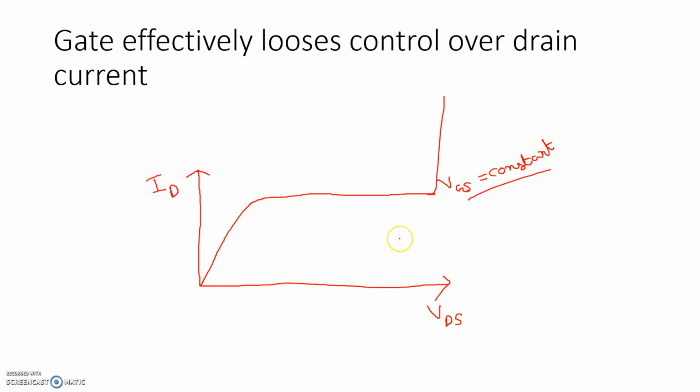So this is the complete graph of the MOSFET characteristics, where we plot drain current on the y-axis and applied VDS, the drain to source potential, on the x-axis. One thing is clear: MOSFET is controlled by gate voltage, right?